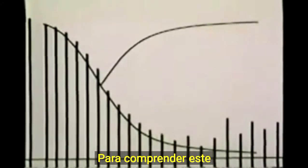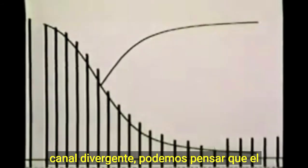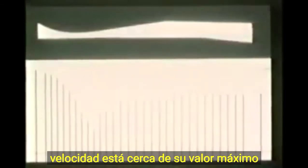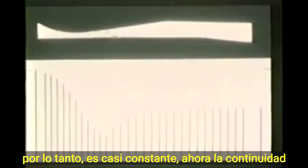To understand this experimental fact of acceleration in a diverging channel, we can think of the Mach number as being so large that the velocity is close to its maximum value for the energy available, and is therefore almost constant. Now, continuity is satisfied to a first approximation by a balance between area and density. The density goes down as the area goes up.